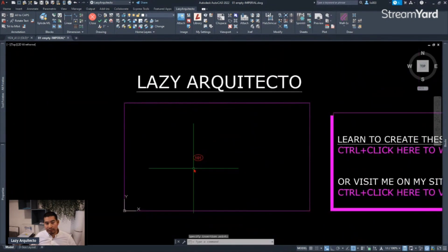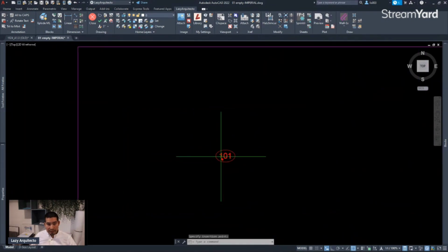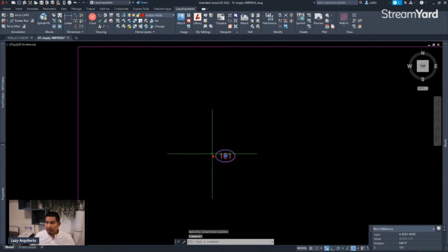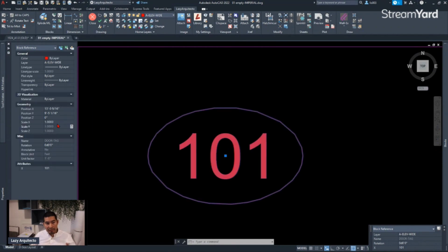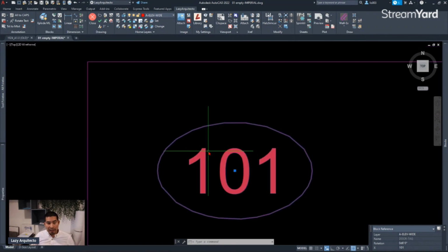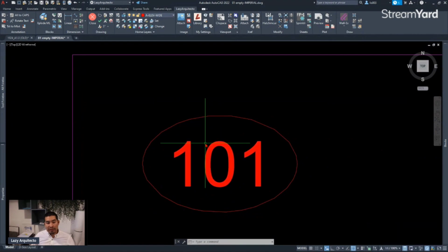drawing, right? So first of all, I inspected the scale. For the scale, I went to the properties and I saw that the scale factors were random numbers. So I set it to 1, the correct scale, and I saw that it was huge, right?